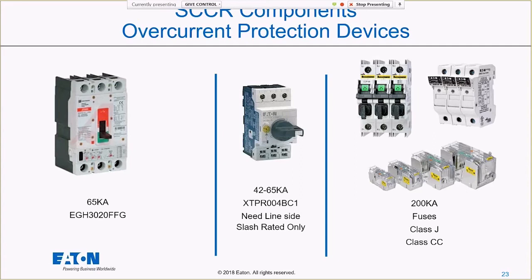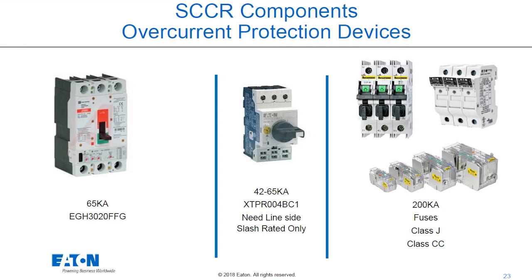Go ahead and use that rock out version of the fuse holder, or just a regular plain old fuse holder, shown there with finger safe covers. Any of those would be perfectly fine in your branches, all just depending on your need for it to be a disconnect, and the application of how you want to be able to maintain something.